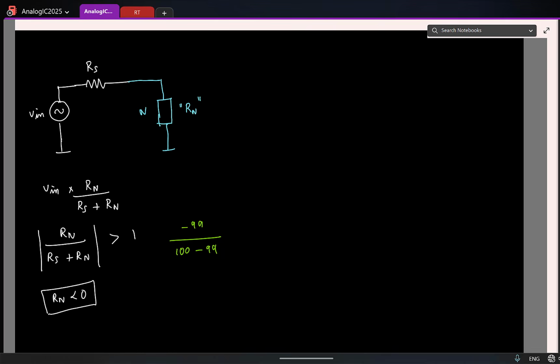Remember that in practice, all the devices we have are passive devices. What do I mean by passive device? They cannot generate power. They can dissipate power or not dissipate power. One thing they cannot do is generate power. And this is the passive sign convention. So let us say I call this voltage V and this current I. What is the power dissipated? V times I?